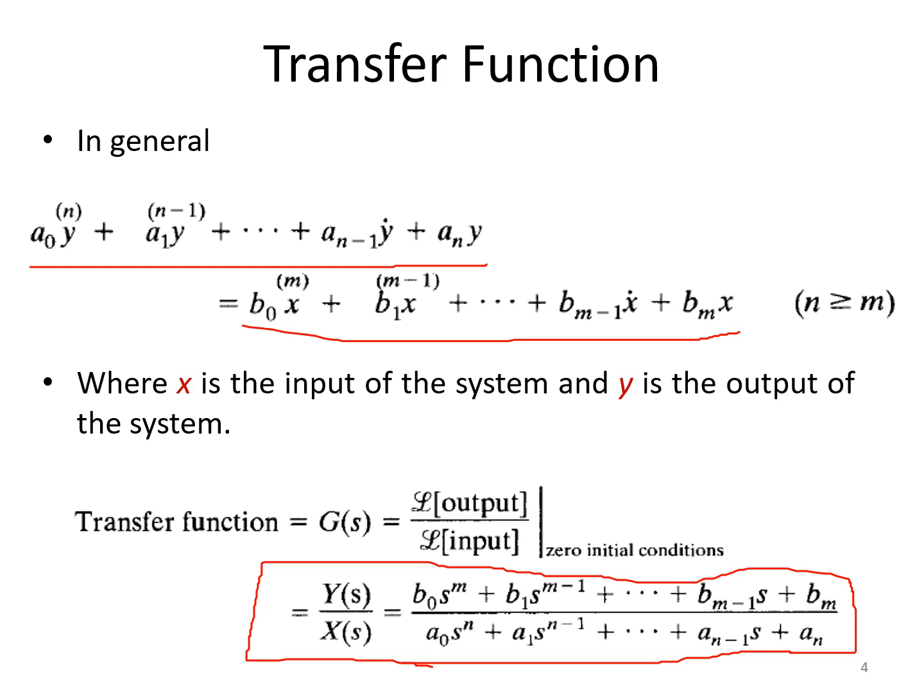Now, why we are going to represent the transfer function using the polynomial representation like this is, if you factorize the numerator polynomials, you are going to get the location of your zeros. If you factorize the denominator polynomial, you are going to get the location of poles. I'll tell you what is the importance of these poles and zeros in the analysis of the system in the upcoming slides later. So I hope this is clear.